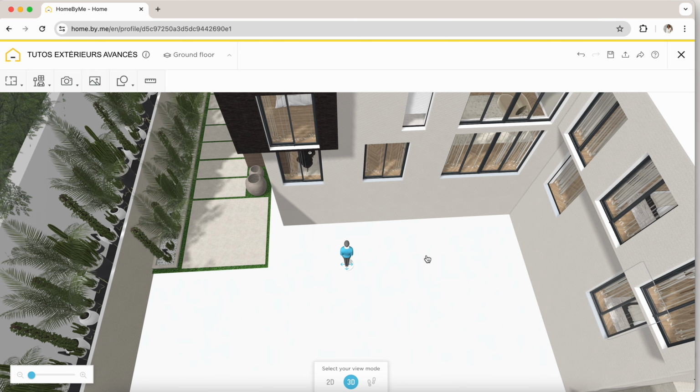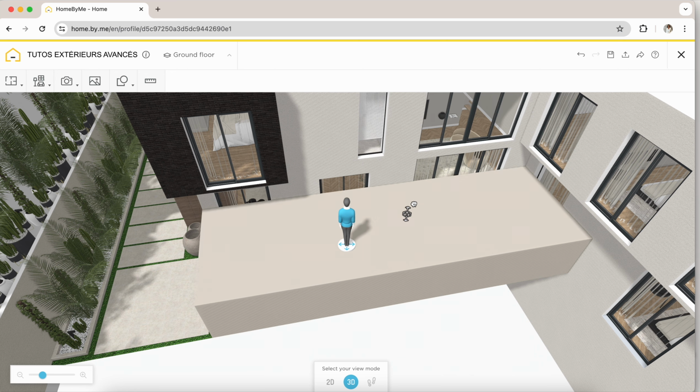By clicking on the surface, a new tab appears, which lets you add an elevation. When you click on this tab, you will get several designs around your floor covering. First of all, on each side, you will have a drawing which simply lets you add a slope on your surface, on either side or the side you want. The second pictogram here in the center is the cube. You can simply add a thickness to your surface.